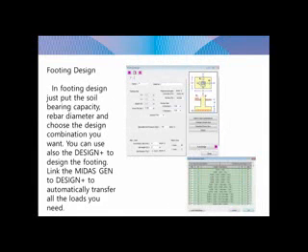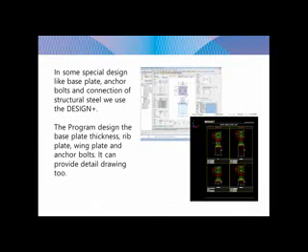You can also use Design Plus to design the footing. Link the MIDAS Gen to Design Plus to automatically transfer all the loads you need. In some special designs like base plate, anchor bolt, and connection of the structures, we use the Design Plus. The program designs the base plate thickness, rib plate, wing plate, and anchor bolt. It can provide detailed drawings too.